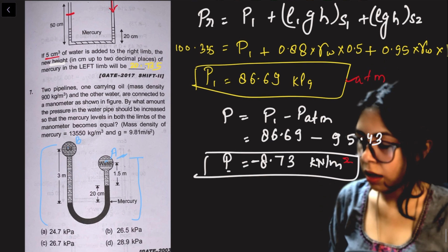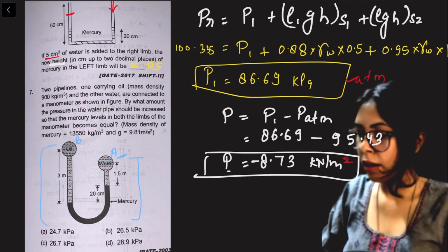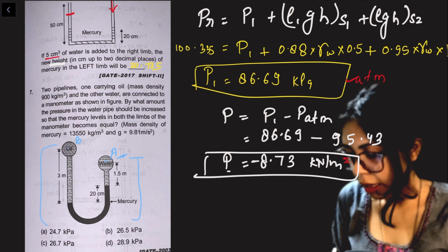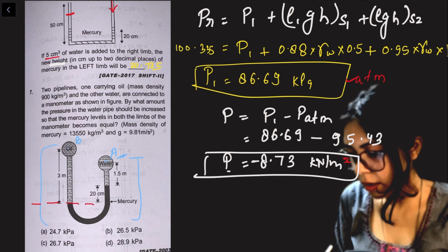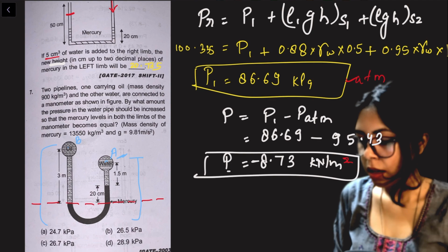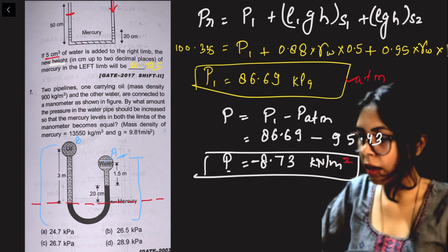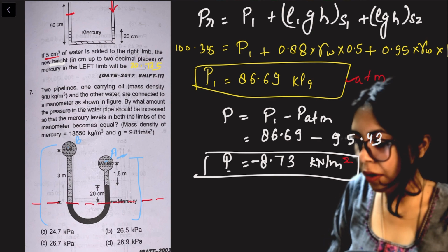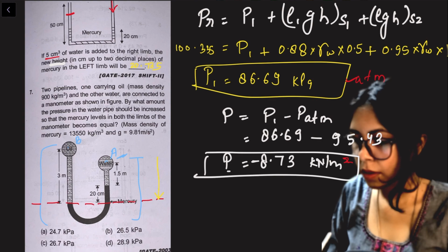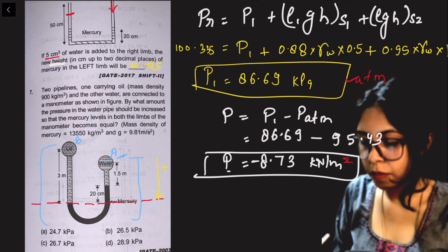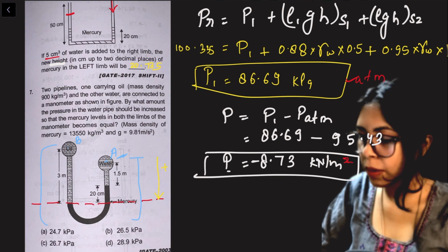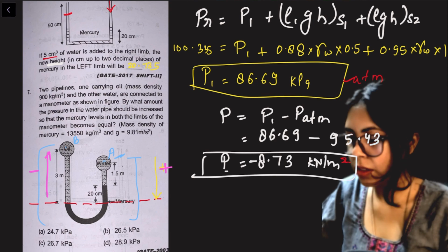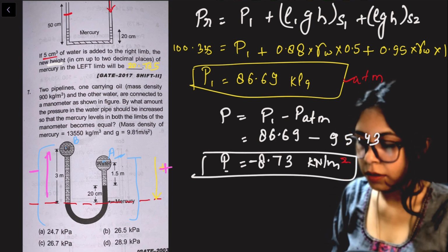So the pressure difference, how can I calculate? I will make the equation. Let's say the datum first I need to select. I will select the datum as this one. Here both limbs are covering properly. So if I write the equation for this datum, from right to left I will go downwards, and downwards positive pressure, you need to remember pressure will be downwards positive and upwards negative. I will put one equation, only one equation, and that will do everything.